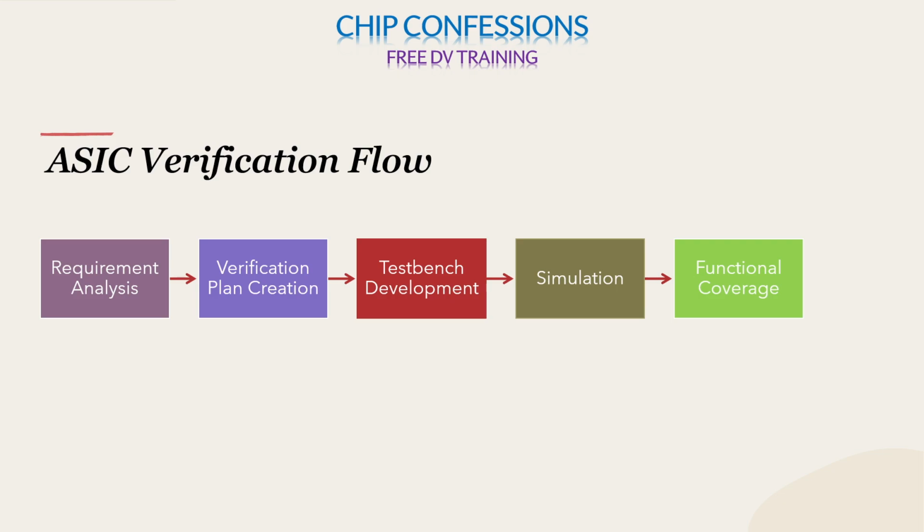And this functional coverage is completely user dependent. We are only listing out the specifications, and only creating the test cases to test those specifications. Everything will be in the verification engineer's hands. Say we have 5 features to be tested and you list out only 4. Though the functional coverage says you have covered the design 100%, as you have missed a feature, you will be missing that 20%, and you will be only 80% covered.